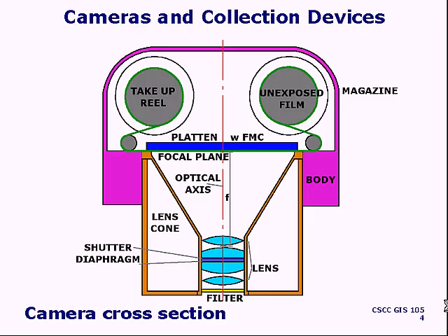It's going to contain all the important electronics, the important controls, everything that's going to drive the film. Of course, it's going to interface with the magazine to make sure that the film can be transported. But the film drive mechanism works in a pattern. You expose the photograph, you release the film, you transport the film, you flatten the film, and then you do the whole thing over again.